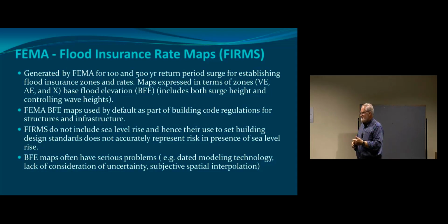So in the history, they keep updating the maps. You think they're perfectly fine, right? But when you do a design based on those maps, what you're doing is saying nothing changes fundamentally between now and whatever the life of the structure is. The return period analysis is the same. The kind of environmental conditions are the same. And that's not going to be the case. So maybe they're good for insurance, but they certainly are not good for designing buildings in the future in the coastal zone if climate change is important, which we think and suggest that it is.